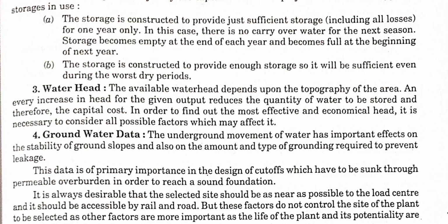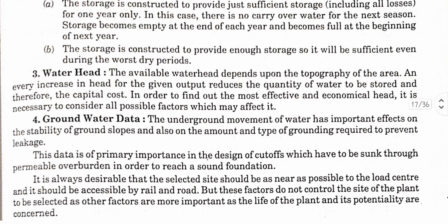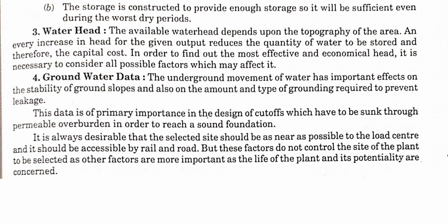The underground movement of water has an important effect on the stability of ground, slopes and also on the amount and type of grouting required to prevent leakage. This data is primarily important in the design of cutoffs which have to be sunk through permeable overburden in order to reach a sound foundation.